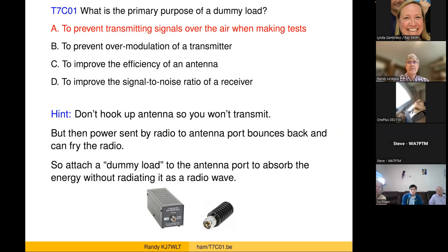Yeah, so if you don't have your antenna hooked up and you want to make sure that you don't fry the radio when you press the push to talk button, which can generate a lot of energy that it tries to send out to the antenna, but if there's no antenna there, it may instead destroy the radio. When you take off your antenna, you can put on a dummy load, and this is a small one that just screws right into the antenna connection on your radio.